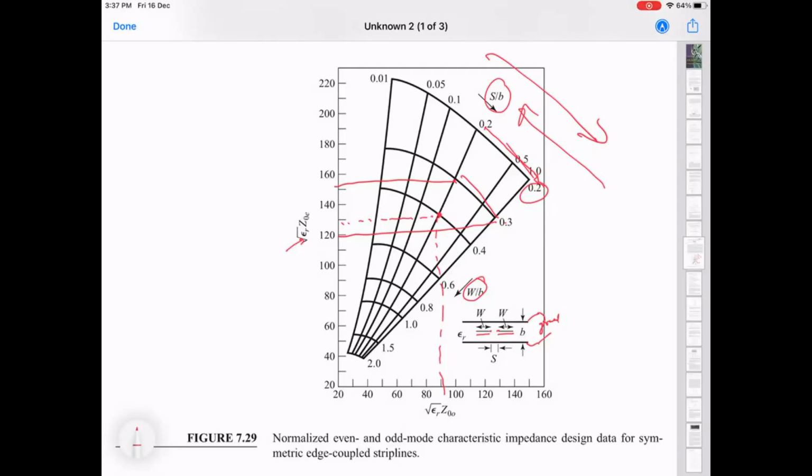They have no meaning, they don't change. I mean, the definition of even and odd mode will not change with the interaction. Sorry? See, the actual value of V1 and V2 is completely irrelevant. Remember, your scattering matrix, which tells you the functioning of whatever network you are looking at, is all about ratios of voltages. So what voltage it is doesn't matter. We are not talking about